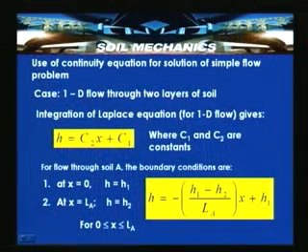Similarly, substituting H equal to H2 and x equal to LA, and solving and simplifying, we will get H is equal to minus (H1 minus H2) by LA into x plus H1. This is valid for distance between 0 and LA. We have not gone to soil B; we are still in soil A, which has a length LA. So, with this we can determine the head at any point in terms of H1, H2, LA and x.